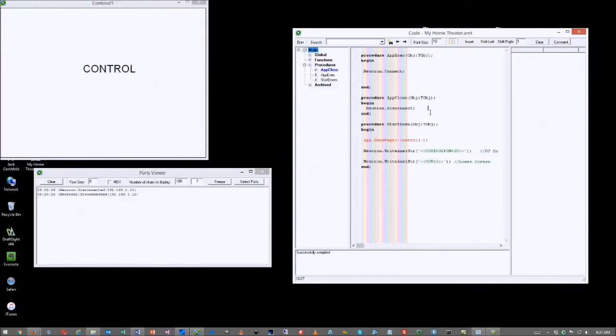So F7 is what I usually do. And you can just press F7, and it went now to the second line. Then you send this, and you can see that when you send the second line in, that line appeared here in the ports viewer. And then the third line, the last line you run, and that's it. So at the end, it's still not running because you already stopped it. So you can remove the breakpoint and just press F9 to continue normal operation.